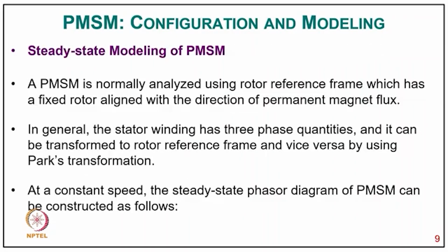associated efficiency. Now, coming to steady state modeling of permanent magnet synchronous motor, a PMSM is normally analyzed using the rotor reference frame, which has a fixed rotor aligned with the direction of permanent magnet flux, and in general the stator winding has three-phase quantities and it can be transformed to the rotor reference frame and vice versa by using Park transformation. At a constant speed, the steady state phasor diagram of PMSM can be constructed as follows.